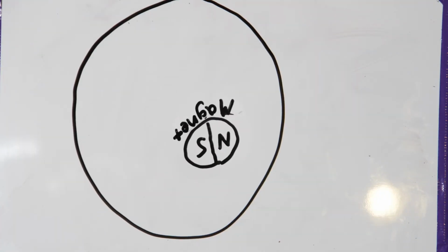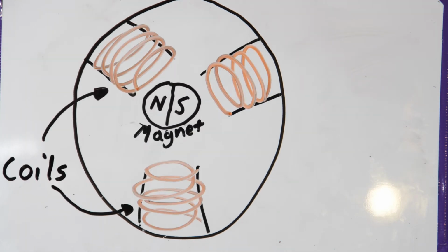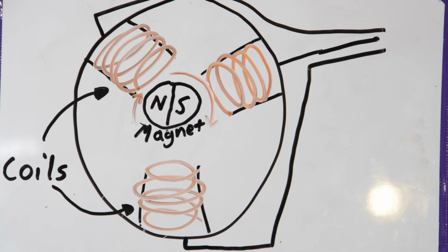I can build the motors using a magnet with 2 poles with electromagnetic coils on all sides of it. The poles in the middle repel the electromagnets on the inside and cause it to spin 180 degrees, because the coils want to align with the magnet in the middle. The poles of the electromagnetic coils are then changed by an alternating current. This alternation in current causes them to rotate again another 180 degrees to align. They then continue spinning due to the constant change in current.